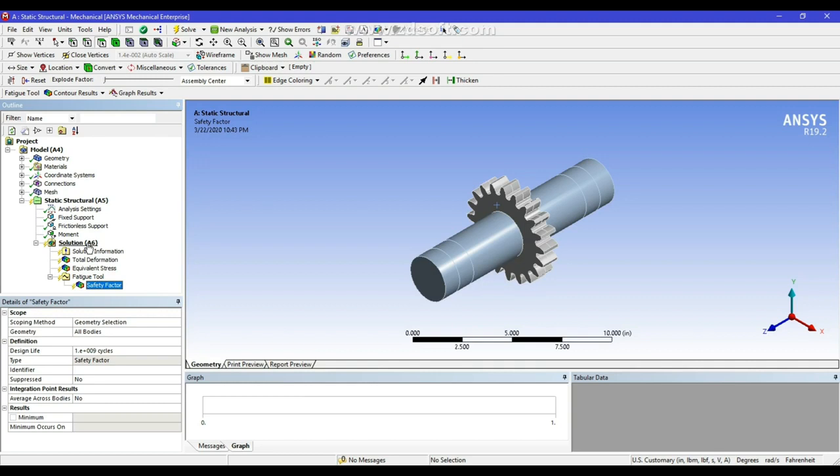Another interesting thing is if the gear is not spur, if this is a helical or a worm gear, there will be some axial force component. So that force requires some other bearing. Those two bearings were ball bearings. So if the gear is helical or other, it will induce some axial force on the shaft, so a thrust bearing and other will be recommended. In this particular video, we just assume that two ball bearings are used at the two ends. So let us solve by this boundary condition, then we will see our final results.